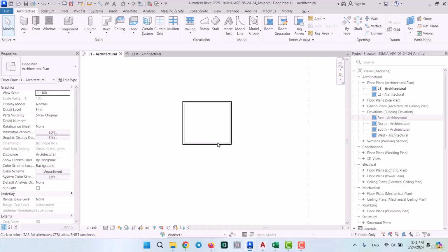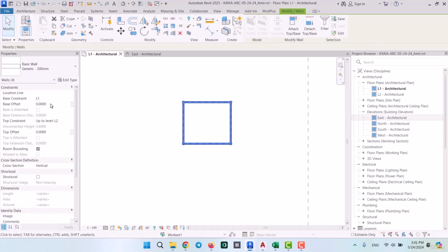After that, you would have to select all of the structural base walls that you've drawn, and then go to their base offset value, which you can find the parameter here, and then change the value by however amount that is needed. That actually isn't a very ideal thing to do, and you should never really do that on your projects, especially when you're working on the bigger ones, because like I said, it's not technically right to do.